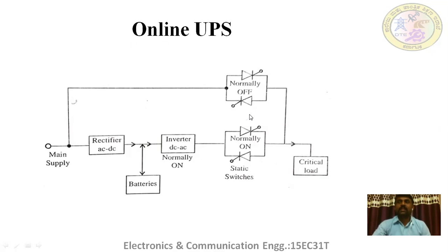These are the static switches or the automatic switches, and these switches can only be activated depending on the conditions of UPS, or in other words, UPS controls power to the load through these static switches. SCR means silicon control rectifier. It is a power device, is the best example for static switch. This normally on static switch is always in on state.